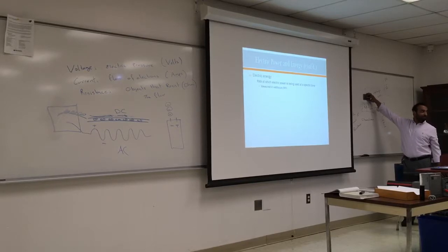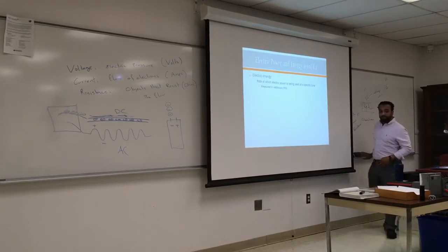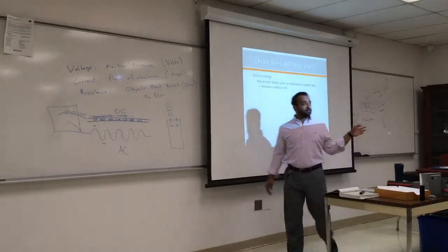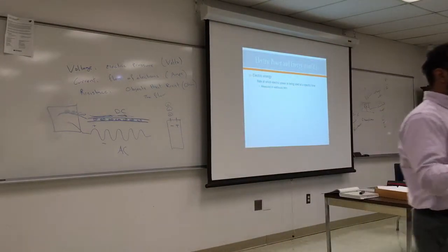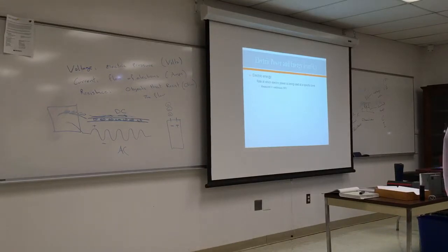That's it. If I want the resistance, I'll cover the resistance, and I'll divide the voltage by the amperage. If I want the voltage, what do I do? Multiply those two together. So the first thing you do when you get any problem with Ohm's law, you write this triangle, and you see what you want to find out, you cover it. From top to bottom, you divide, side to side, multiply. We'll do a lot of examples about that, but it's very, very essential.